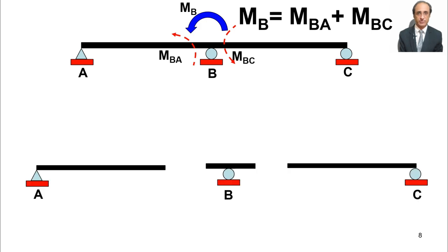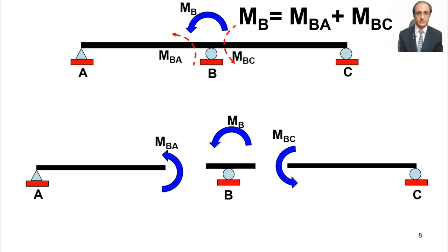These moments are joint moment or member moment? This is joint moment and all these are member moments. These are member forces, these are internal forces, these are the external forces. Sir, for member moment, you have considered anti-clockwise movement positive. So for the joint, you should consider clockwise movement positive. No. Our symbol is anti-clockwise positive, whether member or joint.